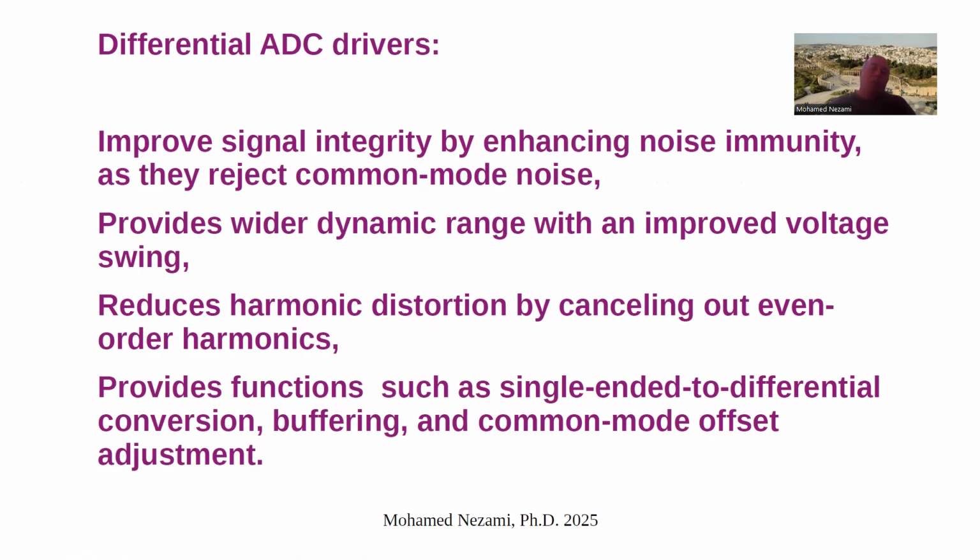This one you can check out of the box how it does that, because when you have a balanced amplifier, basically the odd and even terms, because when you square something, if it has a sign, the sign gets removed. And we subtracted the differences, differential. These things that have even powers, they cancel out, which means second harmonic, fourth harmonic, and so forth.